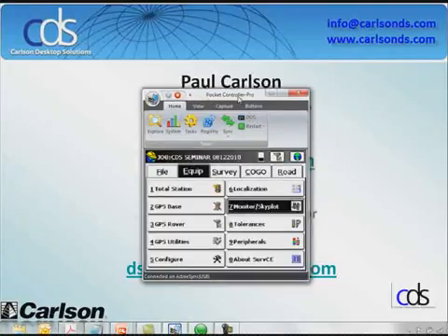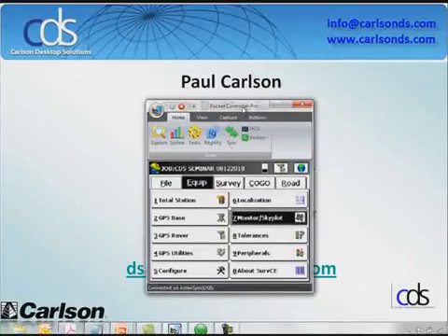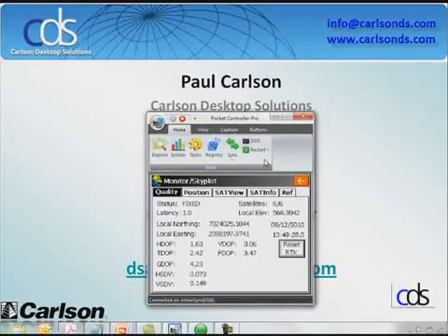So I'm going to go to Monitor SkyPlot. Now, a couple of reasons for going to Monitor SkyPlot. One, this is where I go to check. And two, in this case, there are some things that they added in SurvCE that are really, really nice and really helpful that I want to point out. The very first thing I'm going to look at is that I am fixed. My latency, the number of satellites, and the elevation.